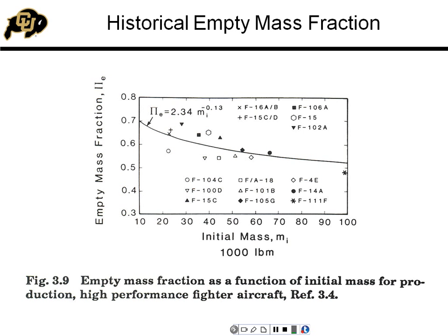So the seminar we're going to talk about looks at this from the aspect of rocket versus air breather versus single stage and multi-stage, and how to think through it. The way that it's done in that case is called a growth factor. Really, it's a sensitivity analysis of all the input parameters and how it drives output, and where you're on a risky slope. I mentioned in the first or second lecture that there's a really strong push in aerospace engineering now, taking a big lead from the nuclear community, to move away from what's called a sensitivity analysis, which is a poor man's analysis of just varying one parameter at a time, to an uncertainty analysis, which is how you take all that information and understand what you're really doing and what the risks are, not just looking at a derivative of one variable with respect to whatever else you're looking at.